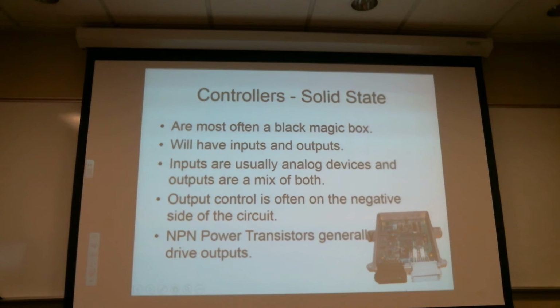Of course, before you do too much, you determine if you have a fried controller. If you have a fried controller, at that point, what you're going to do diagnostically is going to change a little bit, because you're going to be fairly certain that the controller is fried and something outside the controller fried it. Now, more often, and I've done hundreds and hundreds of computer control diagnoses, more often it's either an output device or an input device is giving erroneous data or operating inappropriately.